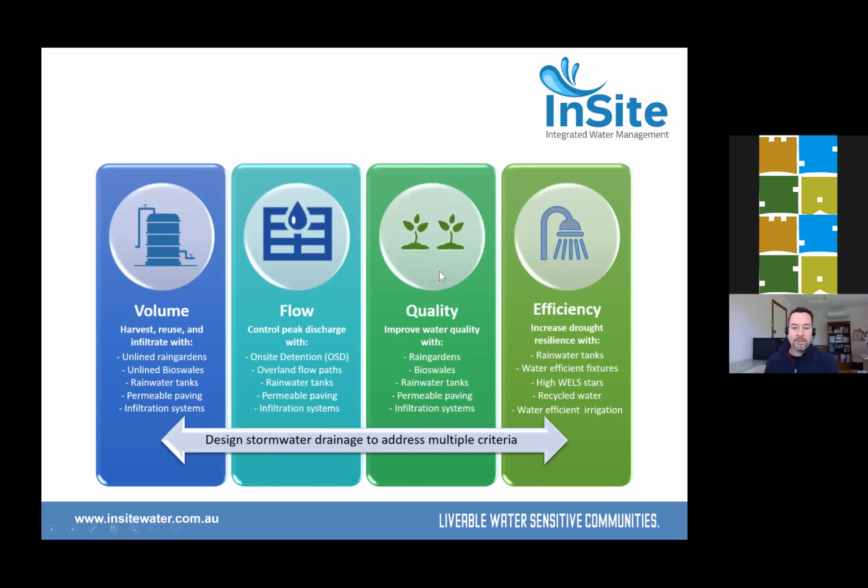Now, it can be used for specific purposes without the other elements. So, for example, it can be used purely to specify an on-site detention system without necessarily specifying these other metrics. However, once again, I'll just emphasize, to meet the requirements of the Australian Rainfall and Runoff Guide and the multiple objectives in the Planning and Design Code, it is better to take an integrated approach and try and meet all of these requirements and optimize your system.